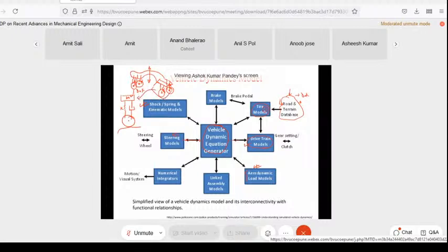Now, let us say you have a motion which is like this, right? Here you see that these two components have the same kind of motion and these two components have the same kind of motion. So it means that we can just have one equivalent from the rear and another equivalent from the front. We can have two, one from the front and another from the rear, and form a half car model, right? So this quarter car model is essentially valid for the upward-downward motion that you come across. And if there is some kind of pitching happening, in that particular case, we look for the half car model.